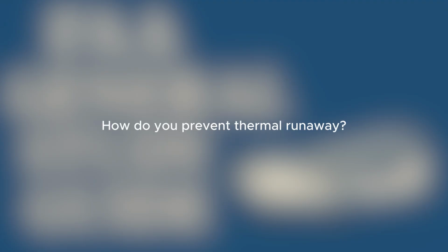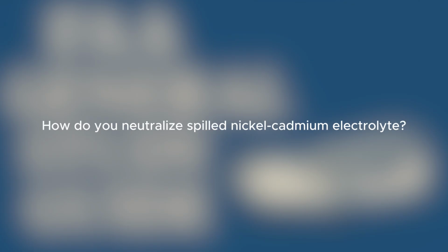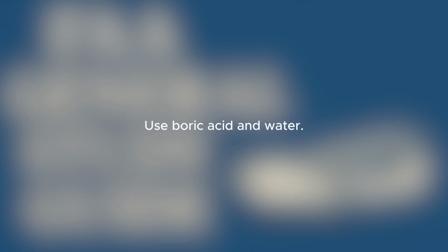How do you prevent thermal runaway? Monitor temperature and control charging current carefully. How do you neutralize spilled nickel cadmium electrolyte? Use boric acid and water.